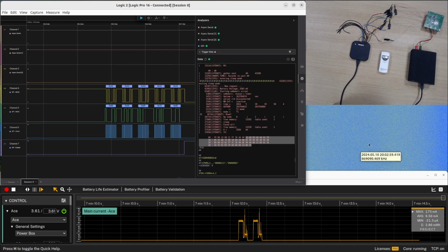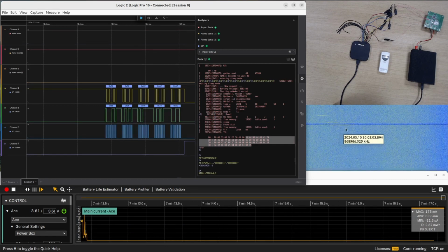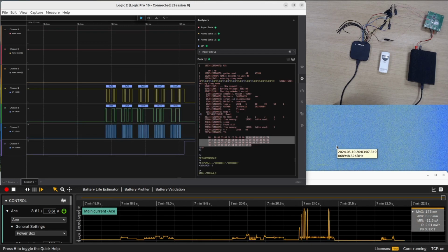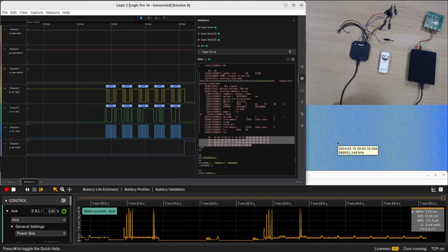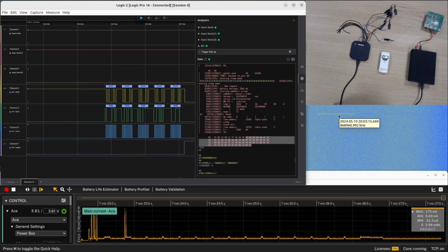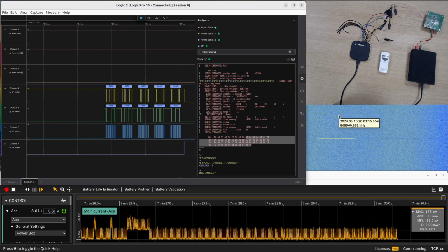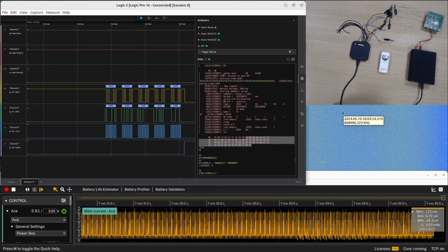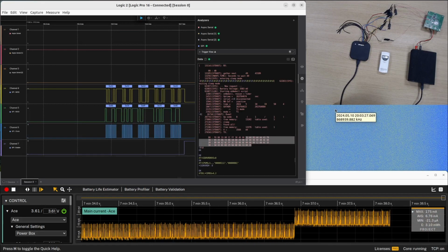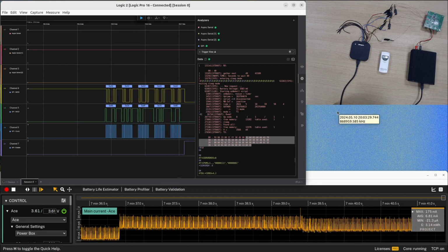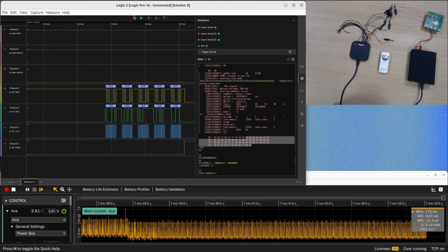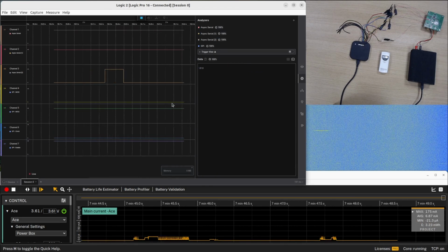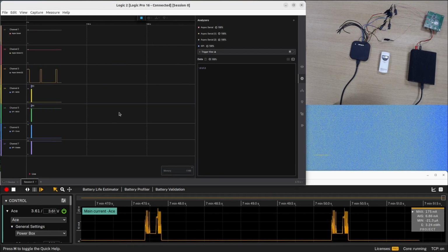Also, I will explain why I'm showing here the SDR. This is the 868.950 frequency, which we could see was set by the receiver, and you can see that every time there is a peak here, it means some wireless M-bus meter transmitted data, and of course the device has to be in the receive mode at the time.